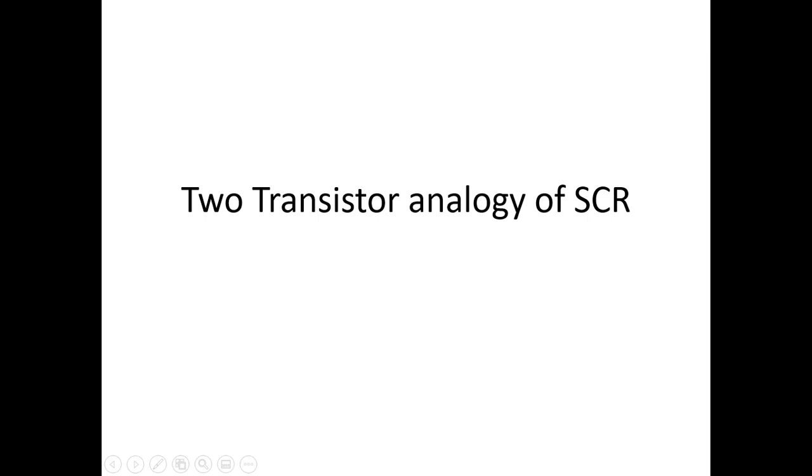So today we are going to see the two transistor analogy of SCR. It's an important question in this unit. The operation of SCR is studied with the help of the operation of two transistors. The SCR can be analyzed as two transistors, one NPN transistor and one PNP transistor. With the help of that we can analyze the operation of the SCR.